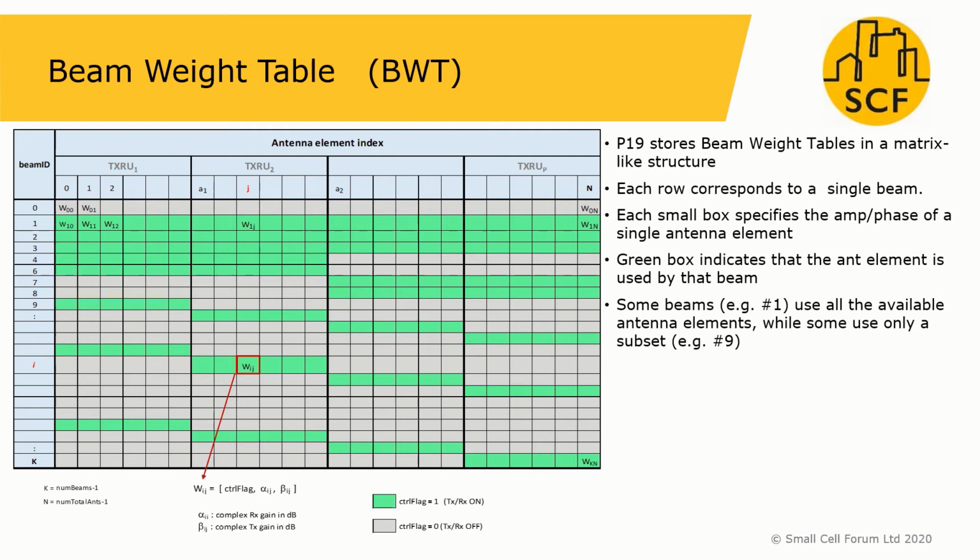of the antenna resources. By assigning non-overlapping subsets of antenna resources, multiple beams can be enabled simultaneously without causing any contention. For instance, beam 4 and beam 7 can be used simultaneously to serve two different UEs which may be located in different positions in space. In the case of beam number 1, however, no other beam can be enabled at the same time, as it is leveraging all of the antenna elements.